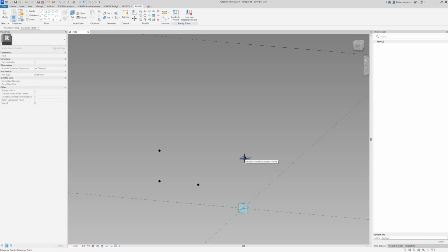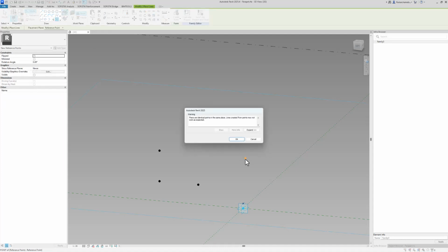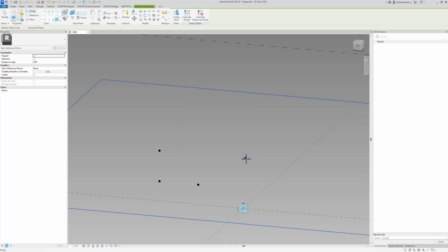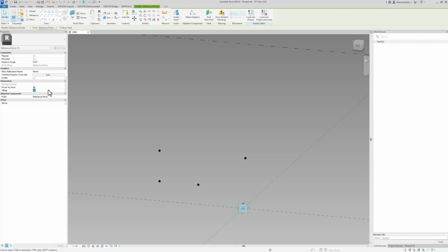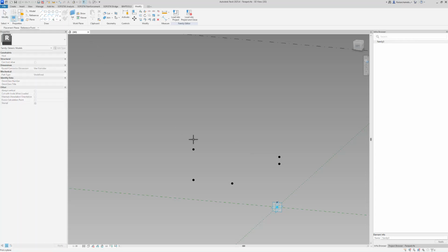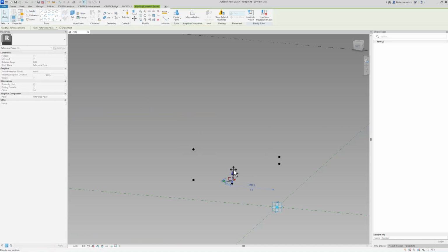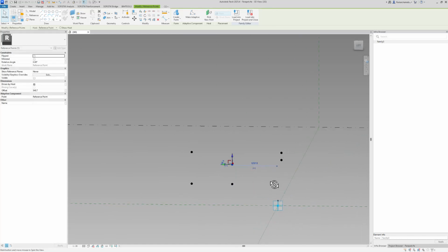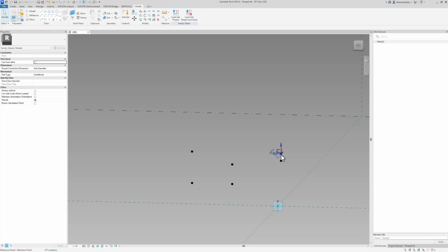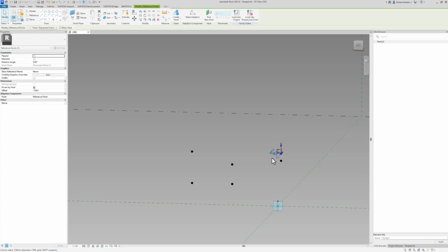So I select the horizontal plane of this point. And just a quick reminder, by creating a new point element directly in its alignment, I now have a new point which I can assign a negative offset of, let's say, 200 to it. A second point, which should be perfectly aligned to this bottom one, should be created. Click on OK. And I can move it up for the references to be assigned. Keep in mind, this point here is now based on this first assigned point, meaning if I move it, the other point will move with it.